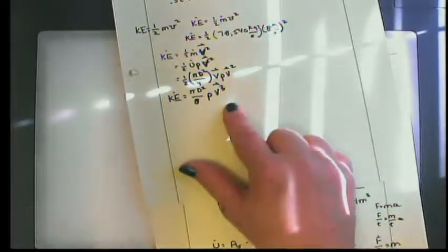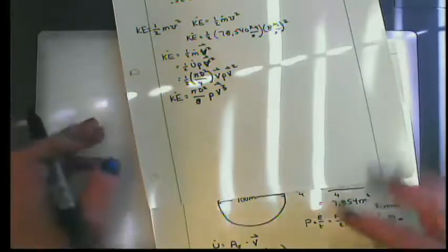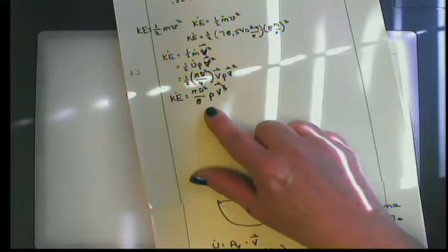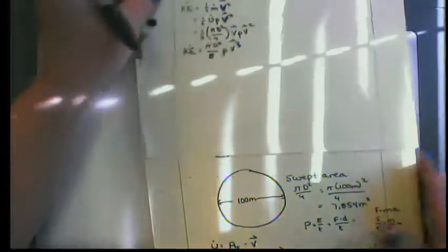And this in general is an equation for the computation of wind power, or kinetic energy available. The efficiency is where it comes in, how good the turbine is, but this is like an upper limit. In other words, you actually can't even get this much, but even theoretically, you can't get more than this amount of energy out of a wind turbine. So I just wanted to kind of stress the importance of the velocity.